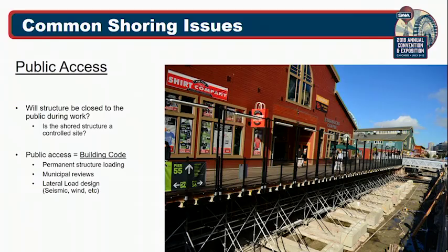Also, in the more extreme cases, you're going to have to design for lateral loads, either wind loading or seismic loading, regardless of how long it's going to be in place. They're going to want to see that thing completely locked down. You want to take all these things into account beforehand, because trying to retrofit after the fact is just an absolute nightmare.